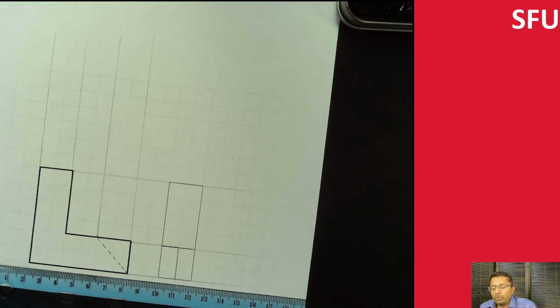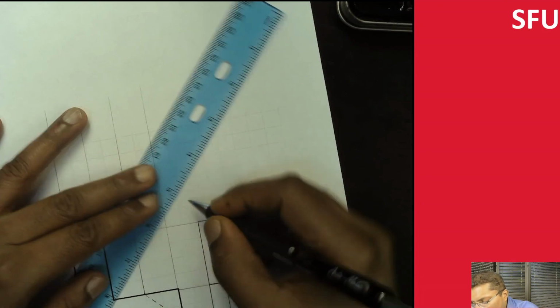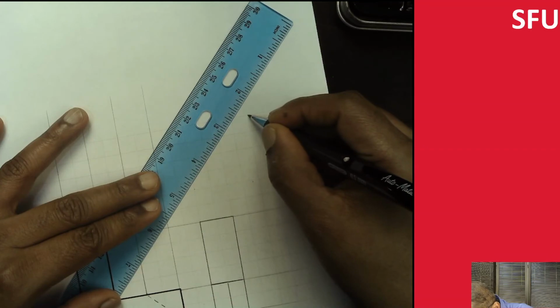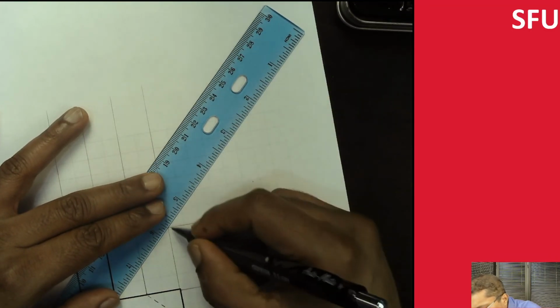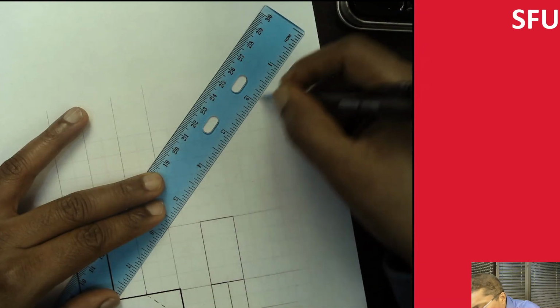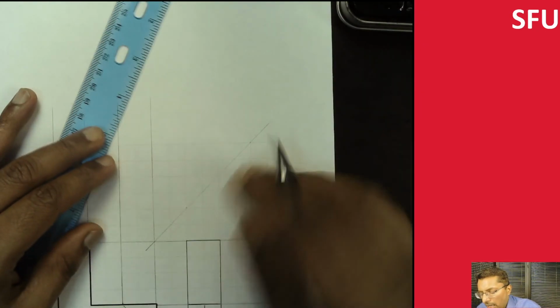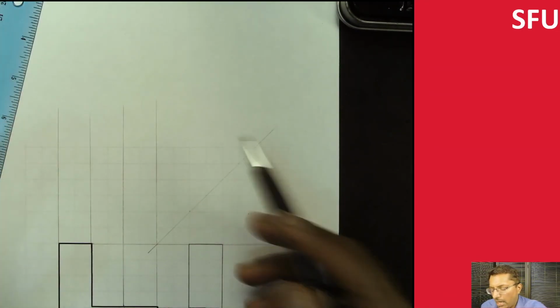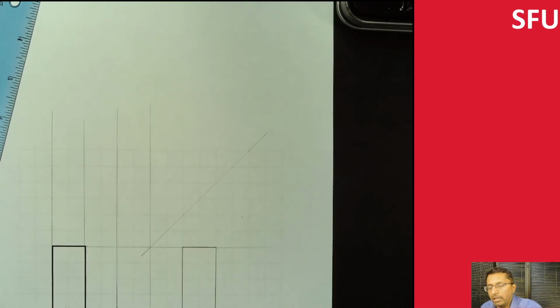So what I essentially want to do is rotate the view really easily by 90 degrees, right? For that, what I'm going to do is mirror it about a 45-degree line. So if I were to draw a 45-degree line, 45 would be here and then pass through this point. So I'm going to draw a construction 45-degree line. Here again, this line could be anywhere, just as long as it doesn't interfere with the object, it's fine. So I can actually move this up and up. But here I just like to put it going through this particular point.